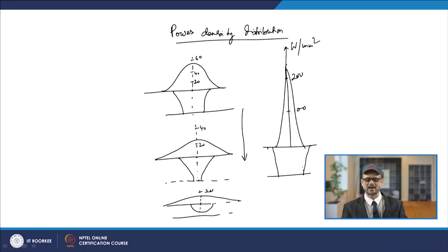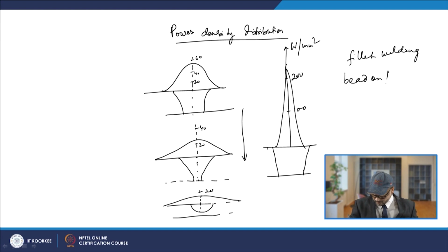The thing is that it also depends under the same heat input and also the same plate thickness. So, if you have two types of welding, the fillet welding and say the bead on plate welding, in that case the cooling time is shorter for the fillet welding.